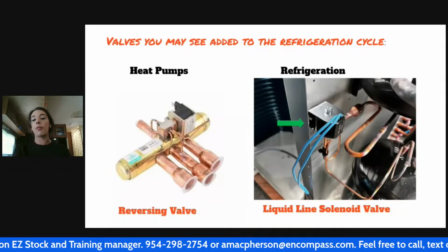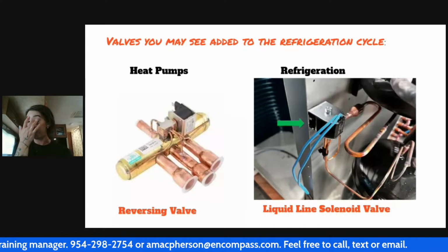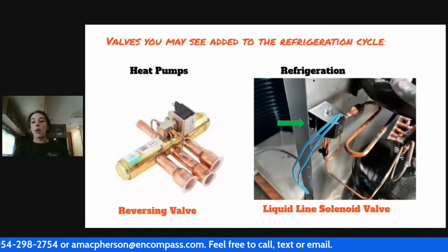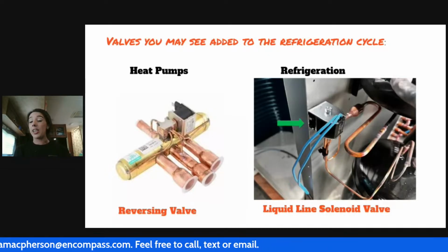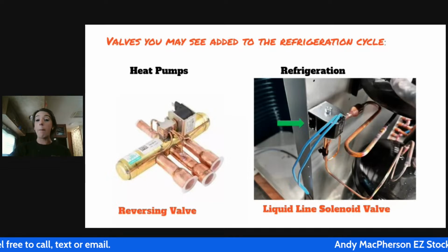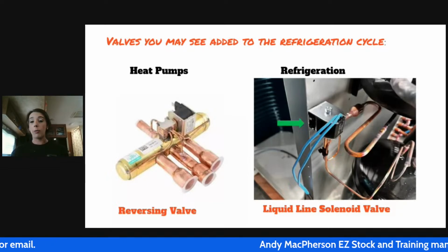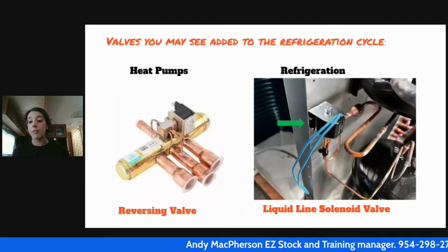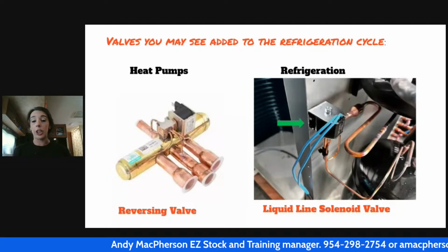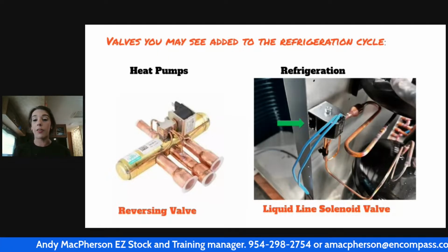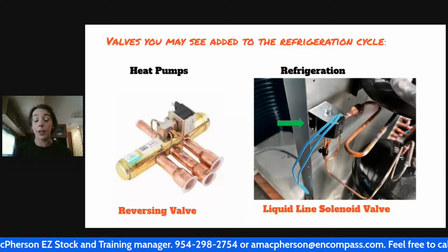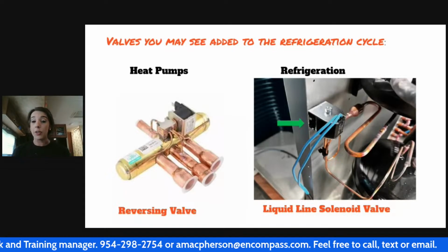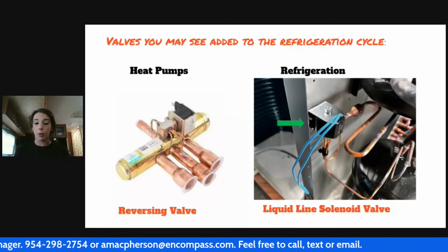And I leave the refrigerant in the evaporator coil, okay? What could happen is now we are dangerously close to the dew point and to not bubbling off any refrigerant at all, which means the refrigerant's not going to be moving because we're not using the unit. So if this unit is shut off, it's at set point, and that refrigerant is just sitting in the pipe, that refrigerant could freeze. It could continue to get colder and colder until the refrigerant molecules freeze.